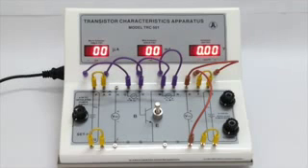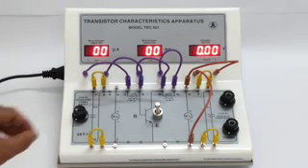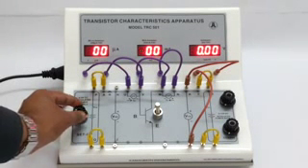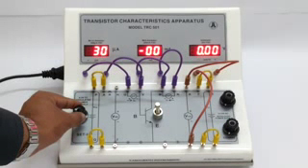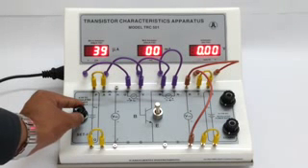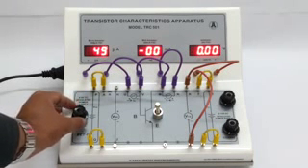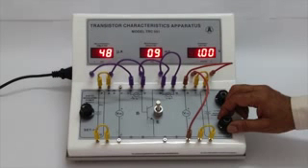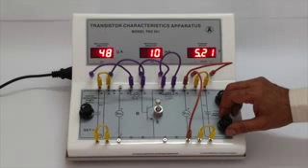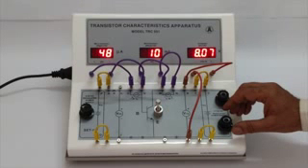By turning the input power supply knob, the base current IB is varied so that the microammeter reads 50 microamps. Keeping IB constant, VCE is varied from 0 to 12 volts slowly in the beginning and then in steps of 1 volt. VCE and the corresponding collector current IC are noted. The same is repeated by keeping IB equal to 80 microamperes and then at 120 microamperes. Then by plotting the I versus V for both the cases in the graph, you get the input and output characteristic curves.